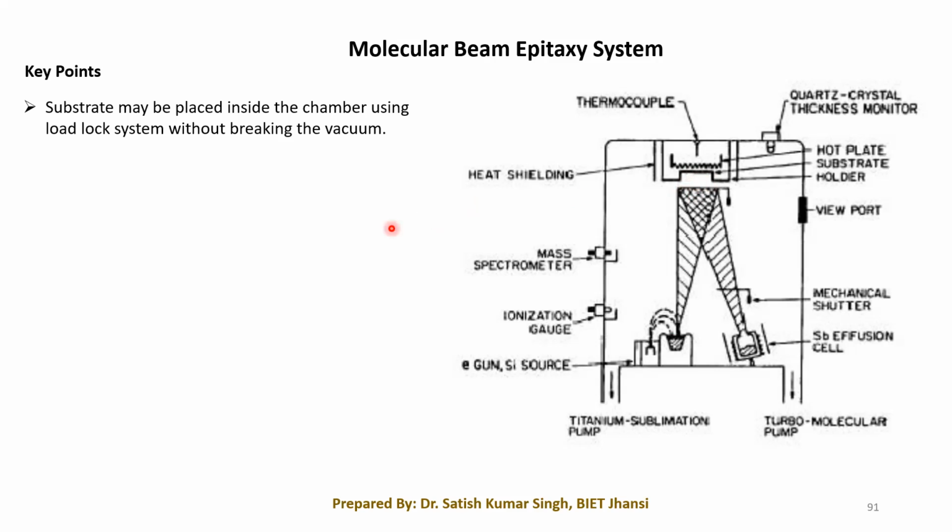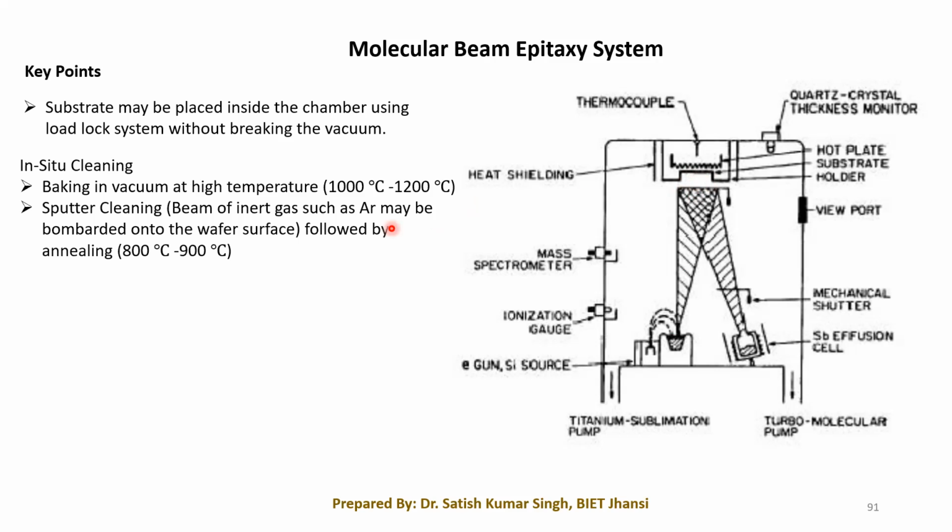Okay, so that in situ cleaning we have to perform first, either by baking it in a vacuum at very high temperature, or by sputter cleaning. This way we can clean the surface first. Now once the surface gets cleaned, we have to go for the deposition of the layer.